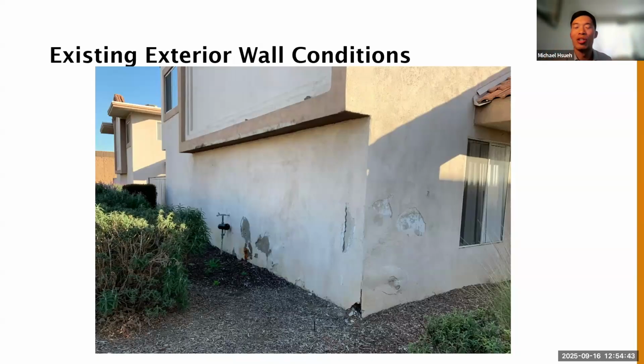So that had its own installation challenges for hanging the panels, but we did incorporate as a part of our design air baffles and sealing at the edges of panels, obviously still allowing for drainage. So that's that balance of handling moisture versus reducing wind washing. And so we reduced as much as possible pressure gradients that allow air to go in behind the panels and reduce the effective R value, but still allowing for drainage behind them because we're assuming that water at some point,